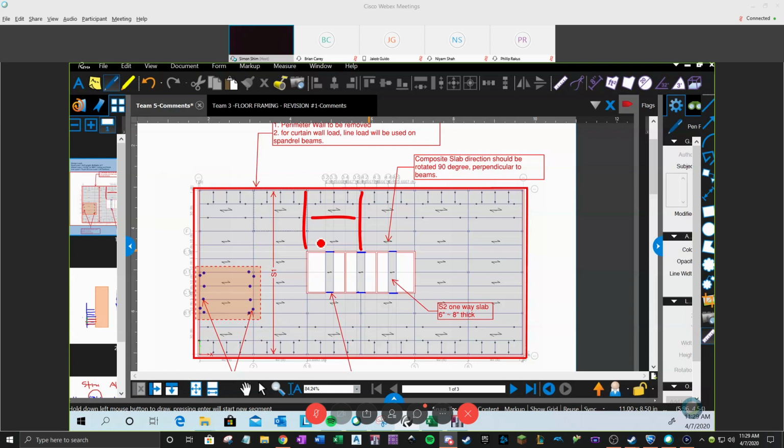And second, the slab and beam orientations have to run perpendicular because that's the load path. The metal deck only distributes loads one way, and it should be sitting on a series of floor beams. So as you can see, when you use ETABS, some elements show the direction of the metal deck. If it is parallel, I think they cannot analyze it. It should always be perpendicular, so the metal deck sits along on the beams.